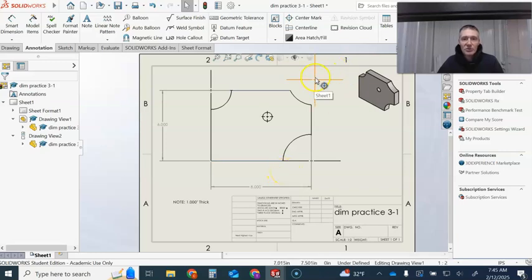All right. So this one's a little bit special character up here. We're going to have to deal with him because we need to make a choice. Do we put the start and stop point right here and the start and stop point here and then give the radius and have somebody else do the math? Or do we actually measure the arc center? Either one is okay. Quite frankly, it really comes down to the manufacturing process and what numbers the people who are going to make this stuff are going to use. That's what it really comes down to in my book. That's my opinion.